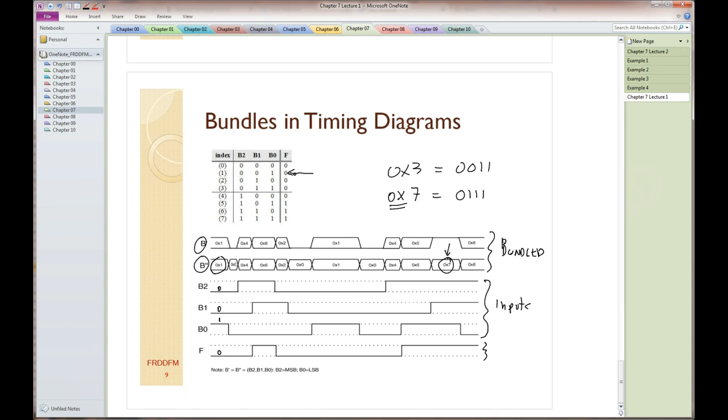So you can follow the timing diagram through and run through these things, but the last thing I want to show in this timing diagram is the fact that when all the signals are 0 or all the signals are 1, we can actually represent it differently in the timing diagram. So these are examples of when all the signals are 0. You can see it matches a 0 on the bottom. You see this often in timing diagrams. Certainly you want to use it if you think it makes your timing diagrams clearer. Here's an example of when all the signals in the bundle are a 1.